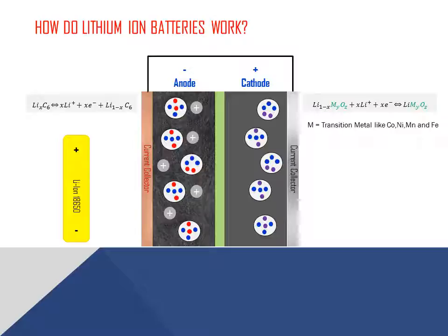It is important to note that lithium-ion batteries are called by the chemistries of the cathode materials. On the opposite side, the anode is made out of graphite or lithium titanate or silicon-based materials. The battery cell is submerged into an electrolyte, a material that works as a transport medium, allowing lithium ions to diffuse freely from one electrode to the other. This electrolyte is commonly a lithium salt in a carbonate solvent, like lithium hexafluorophosphate.